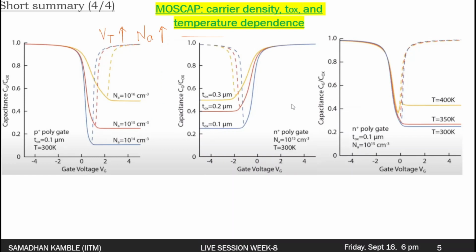Going to the next parameter, that is the thickness of the oxide, in this case we are talking of an n type substrate, that is PMOS. For PMOS, the thickness does the same as the charge carrier concentration does. So the magnitude of the threshold voltage also increases when Tox is increased. These plots sir has done in that utility.